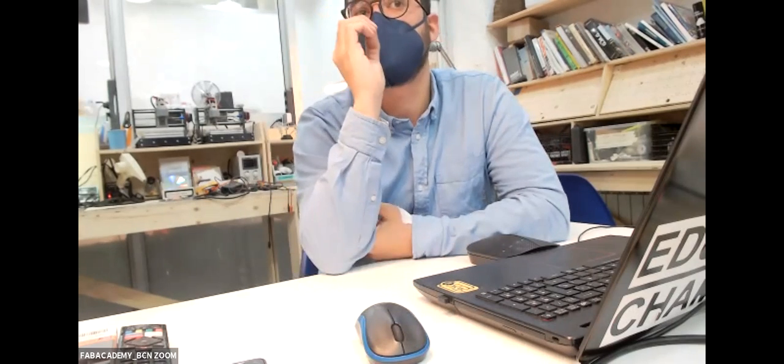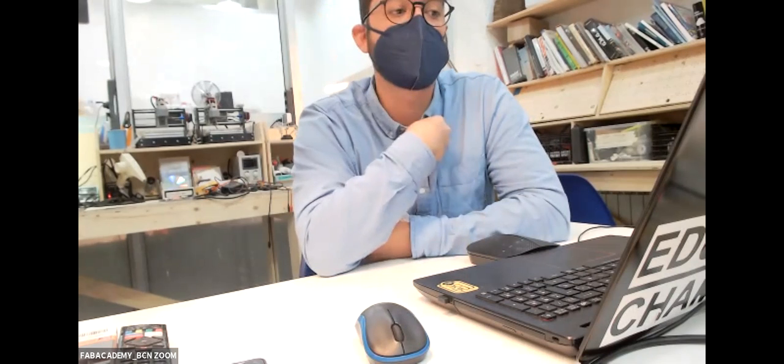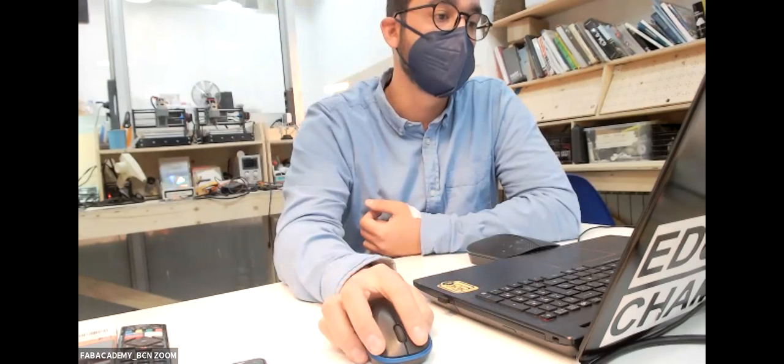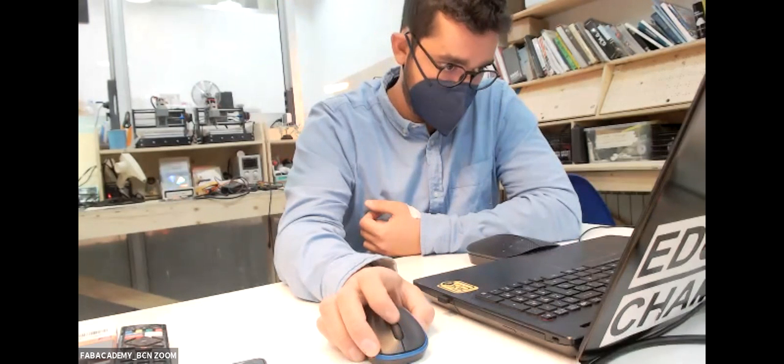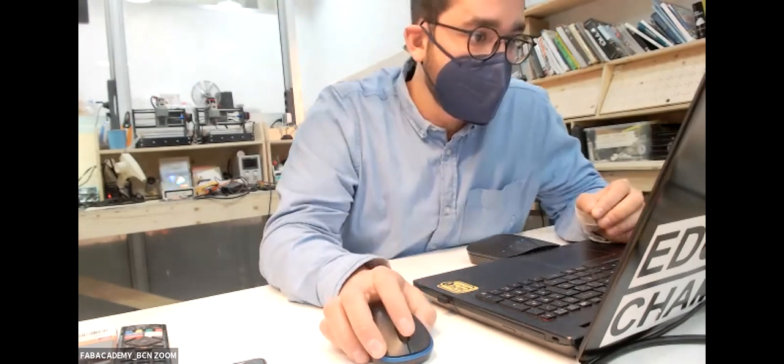Carbon fiber, for example, you have a problem. Carbon fiber dust is really toxic for humans. It's really bad for the lungs. So you can invent your own solution. Usually you need a HEPA filter to actually take the dust out. If you don't have a HEPA filter, which is usually quite an expensive machine, what you can do is... this is milling. Yeah.